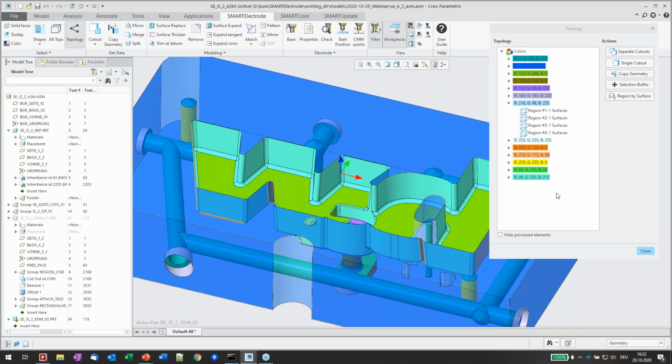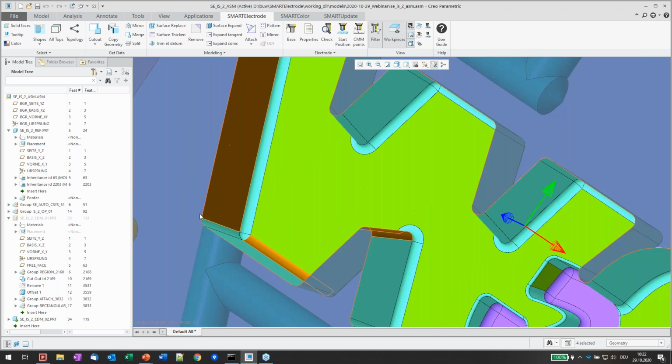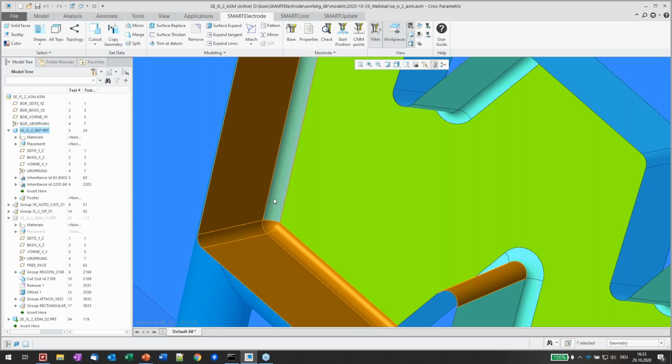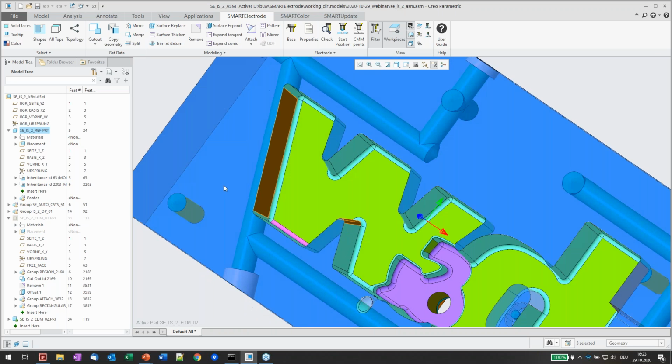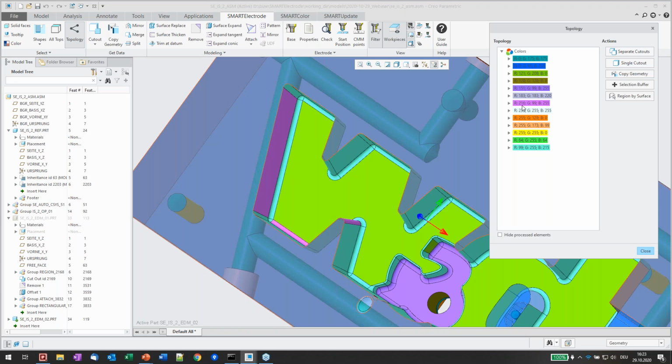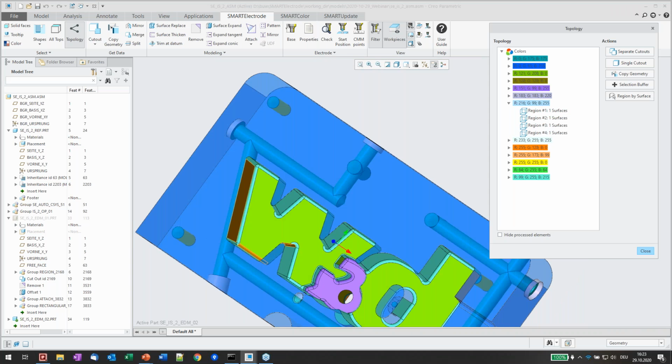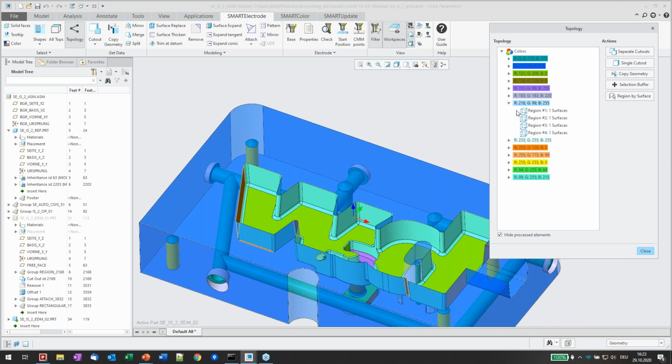And what I now would like to show you is if you want to detail the current selections a little bit more, you can add the selected nodes to your current selection buffer. So you can close the user interface, and if you want to add more surfaces to the selection or deselect some surfaces, you can redefine this through the whole process. And you can also remove processed items from the list.